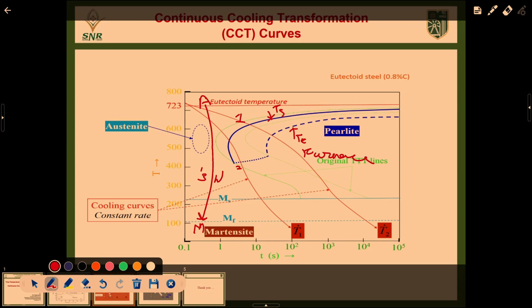Compared with time temperature transformation, CCT is entirely different. In time temperature transformation, we only check how the temperature changes over the time period. In the continuous cooling transformation diagram, we have the same time and temperature, and one extra thing: we can add the cooling media. Based on the cooling media, we understand how it transforms. So come to the next slide for better understanding.